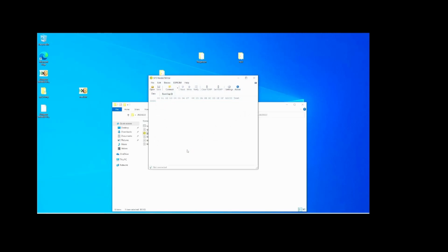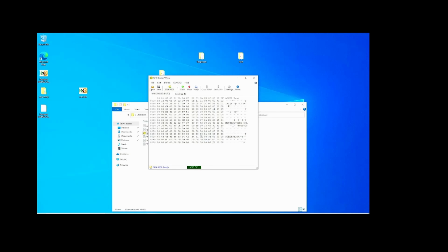Then we can go connect. And here you can select the chipset as a flashing device. We connect and now we can read. We have to specify the EEPROM device. In my case it's 82. And this is the SPD of a 16GB unbuffered ECC stick that we just read here.